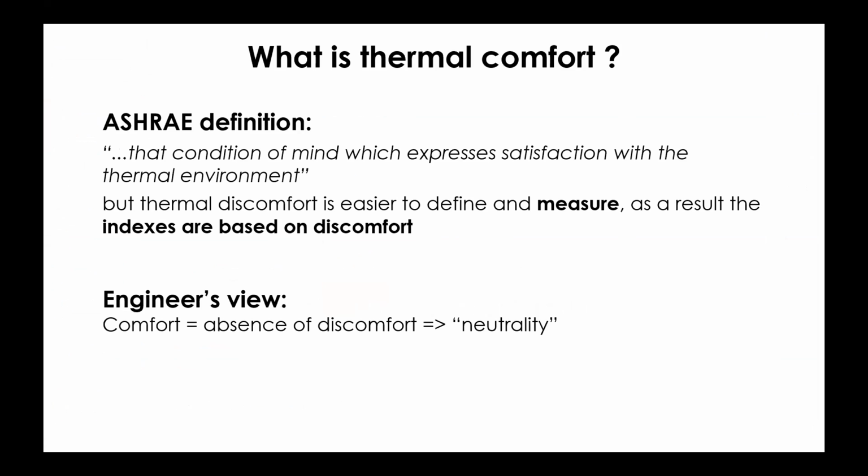Regular view. Okay, good. So, thermal comfort. What is thermal comfort? The ASHRAE definition: that condition of mind which expresses satisfaction with the thermal environment. But in fact, it is typically measured as a result of indexes that try to look for discomfort as opposed to comfort. So in an engineer's view, comfort means that you don't have any degree of discomfort. And this obviously is a bias that changes the way that it's measured.